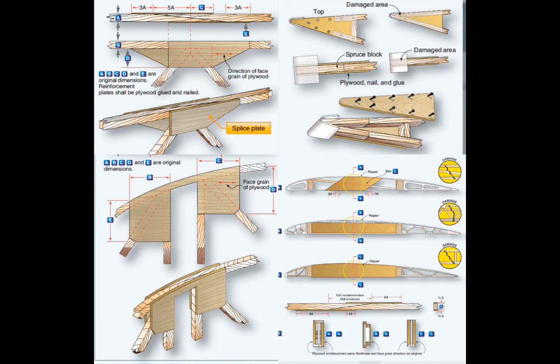What are some of the various methods used to apply pressure to joints in aircraft gluing operations? Brads, nails, screws, clamps, or hydraulic and electric power presses. Why does the strength of a scarf joint depend upon the accuracy of the two beveled surfaces? Because an inaccurate bevel will reduce the amount of effective glue area.